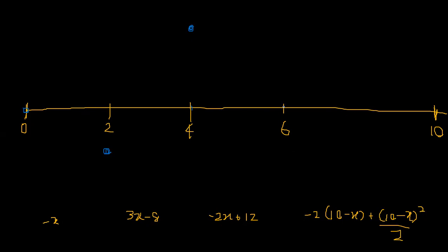So at x is equal to 6, 6 into 2 at here. Can you see at the hinge, what is the bending moment? 6 into 2 means minus 12 plus 12. It is 0, right? So as we expected, at the hinge, the bending moment is 0, right? So at x is equal to 10, bending moment is 0. Does that mean it is a straight line? No, right? It is a curve, right?